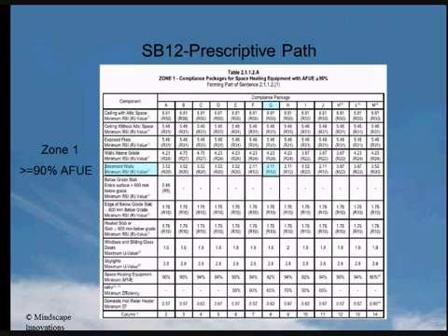The below grade slab, where the entire slab is more than 600 millimeters, or 2 feet, below grade, does not need any insulation. However, when the slab is within 600 millimeters of grade, the edge of the slab needs to be insulated with at least R10 insulation, extending no less than 600 millimeters below the exterior ground level. As well, when the floor slab is within 600 millimeters of grade, the entire slab must be insulated to R10. If the slab contains heating elements such as ducts, pipes, tubes, or cables, the heated area that is in contact with the ground shall be insulated to R10.